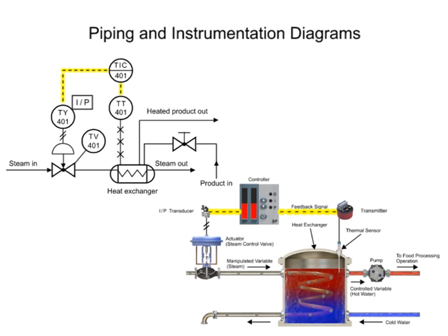A dashed line between components indicates an electrical signal. The controller and indicator is the instrument where the transmitter sends an electrical signal and is shown in the functional identifier at the second and third letters, I and C. Balloons with a solid dividing line indicates that the instrument is board-mounted. An electronic signal from the controller is indicated by the dashed line.